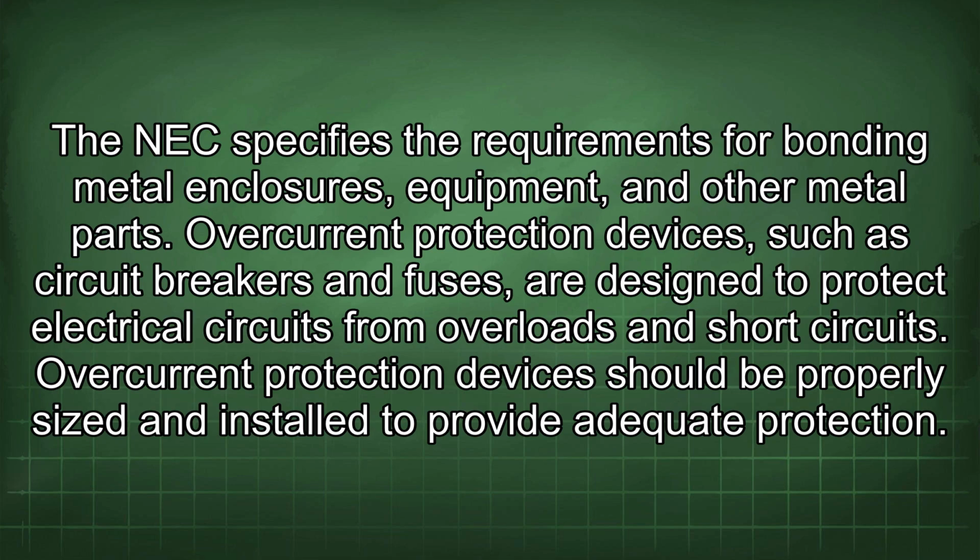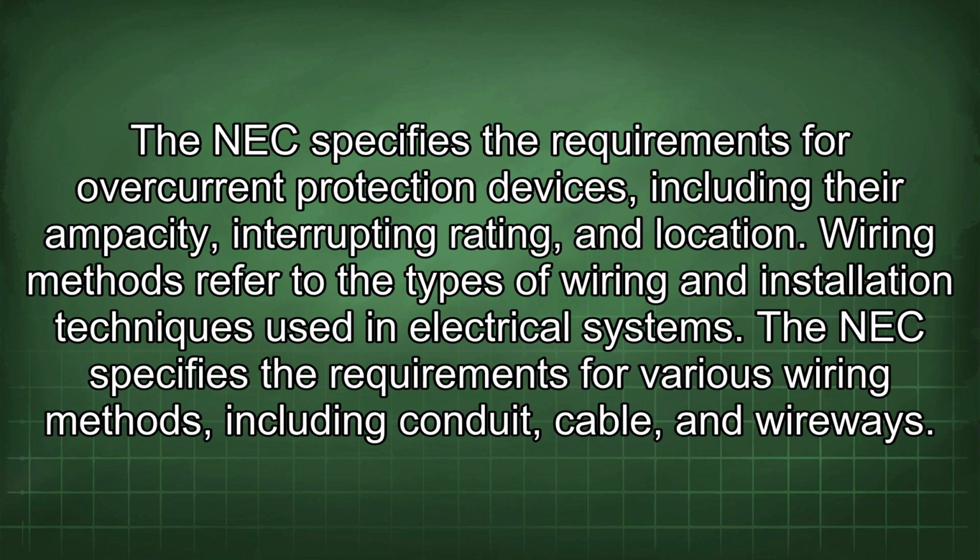Overcurrent protection devices, such as circuit breakers and fuses, are designed to protect electrical circuits from overloads and short circuits. Overcurrent protection devices should be properly sized and installed to provide adequate protection. The NEC specifies the requirements for overcurrent protection devices, including their ampacity, interrupting rating, and location.